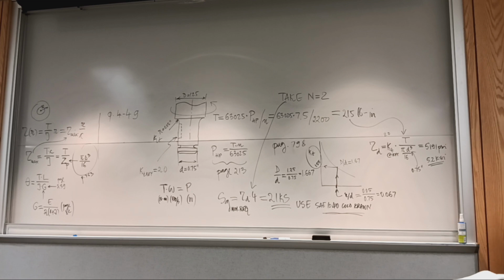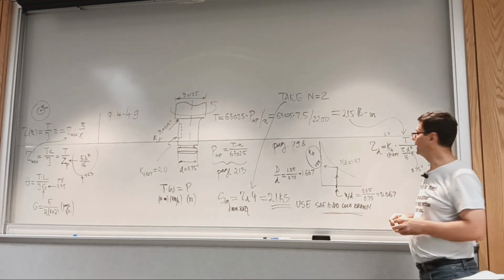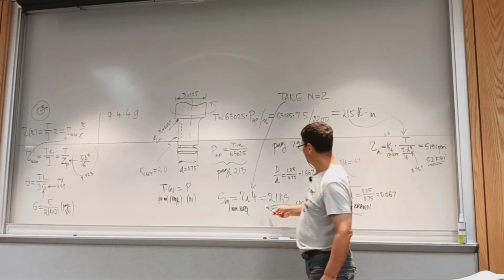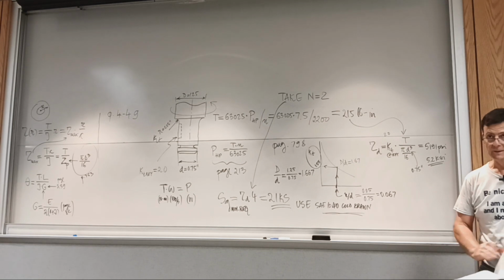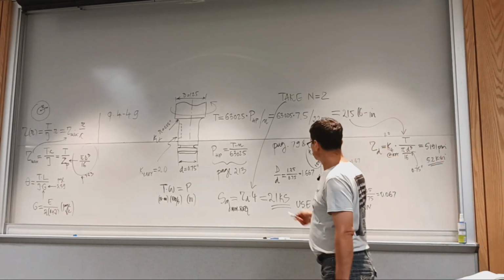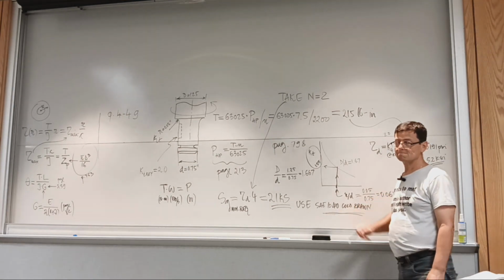Okay. All right. We were doing the math real quick, assuming there would be a lot of impacts like hitting your steel rod. Well, we're still way away. I mean, even if you go with the highest of the stress riser or at the design factor, 62. This is still okay, even for that instance.